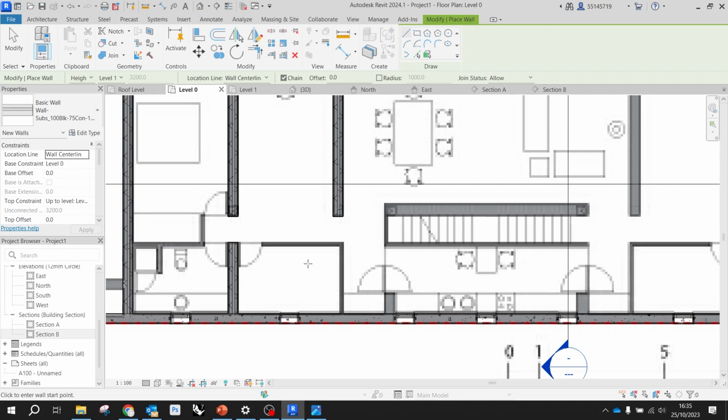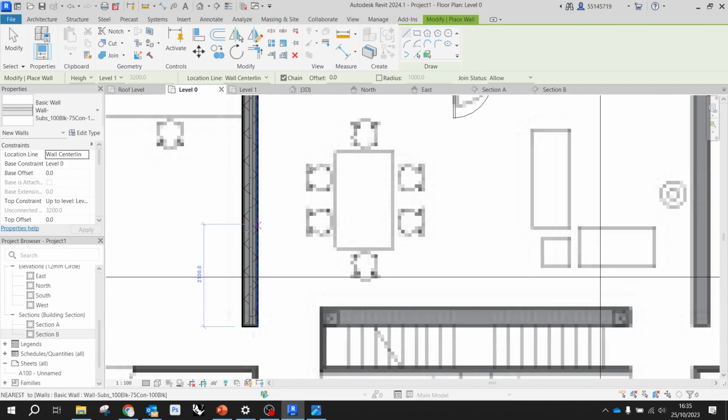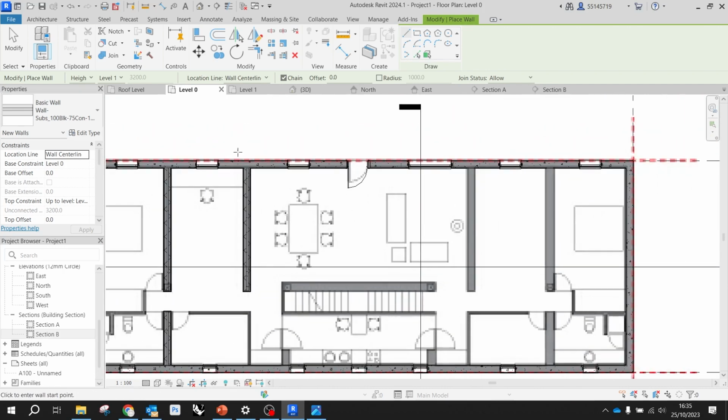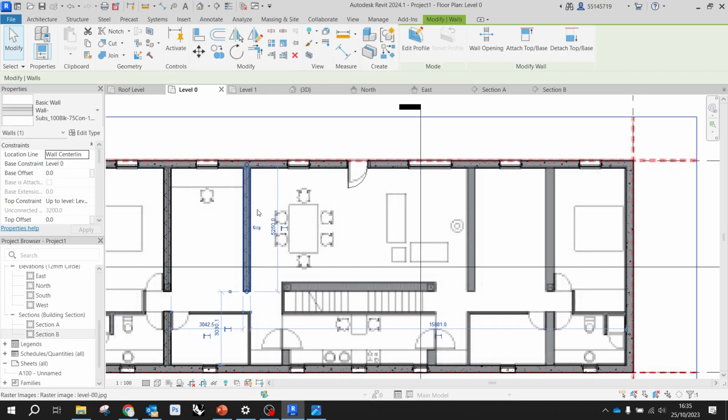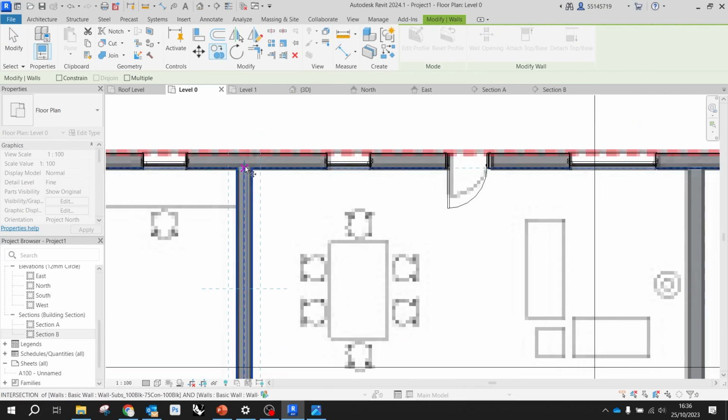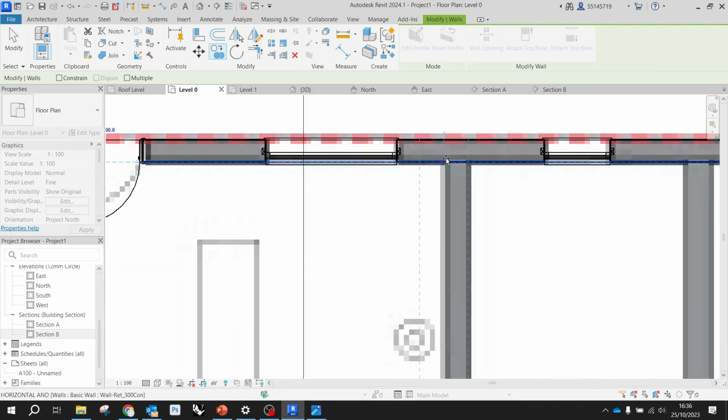Okay. So, just do this. What you can also do is select big elements and copy them. So for instance, I can see that this wall is going to be pretty much the same, but replicated in here and there. I'm just going to do copy, grab the base point from where I want to copy to, and then maybe somewhere in here.